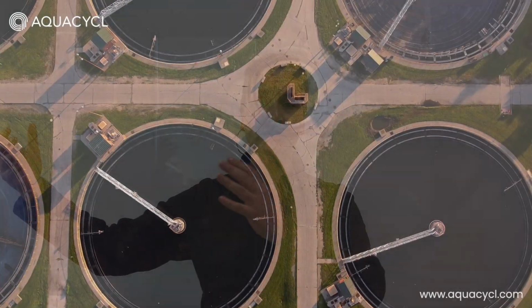For waste-activated sludge, which has to be managed from aerobic processes, right? This is that aerobic bacteria that's growing up to keep up with the organic pollutant removal that's required based on the amount of sugar coming in and air that's forced into the tank that they're growing in. So you get a lot of sugar and you get a lot of air, you get a lot of biomass. Some of that gets returned, right, and reused because you want to keep that process going with sludge that's been acclimated to it. But all of the excess stuff has to be removed.